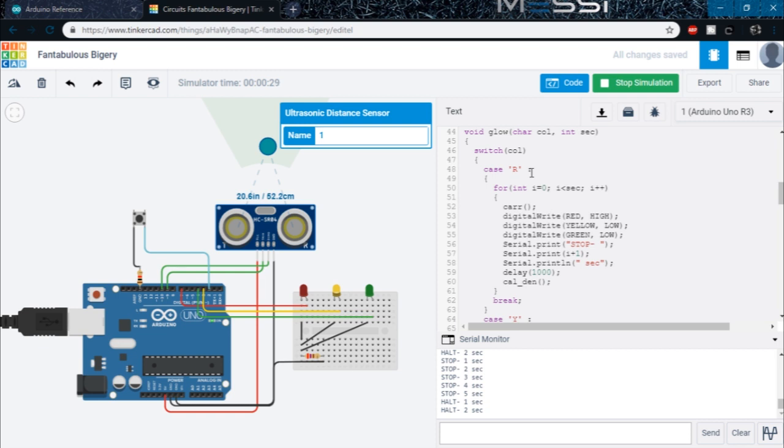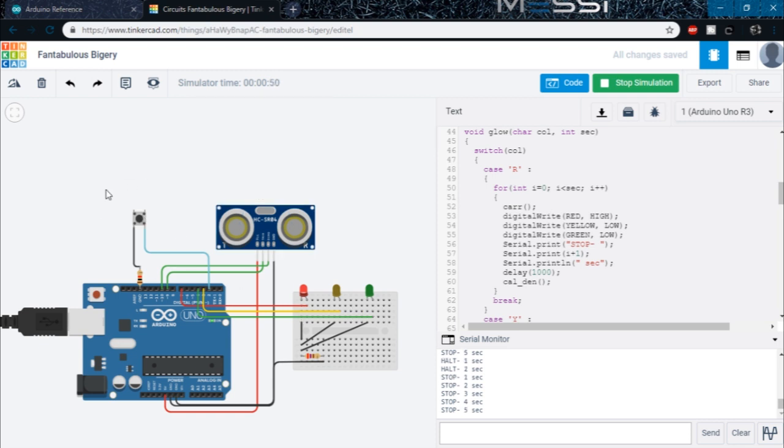In the whole code, this has 1000 points. If we can build it, we get 1000 points, otherwise we do not. So how to design this? Now there are several ways you can do this, like checking whether the button is pressed in the for loop in each of these loops, but that will not work, or fail rather, because we have used a lot of delay. Suppose you have pressed the button while your program is on delay, it will sense nothing.